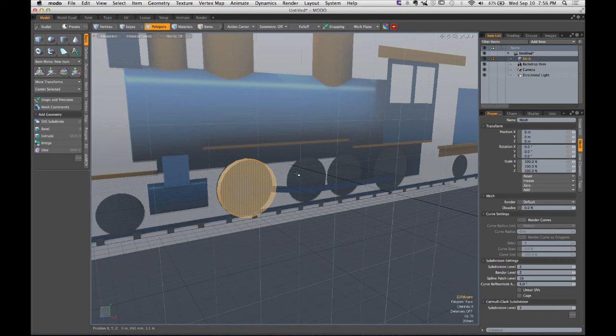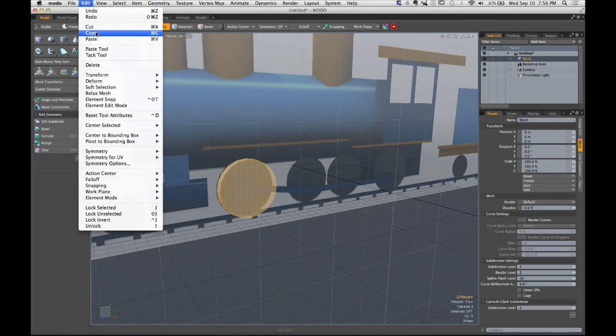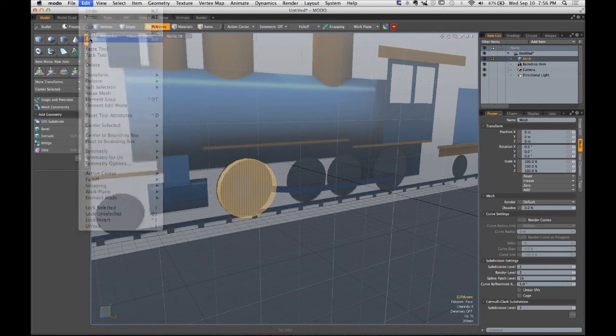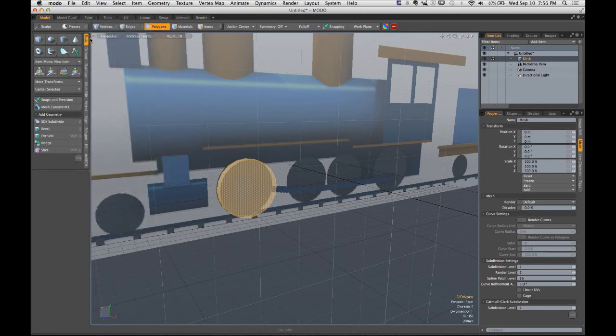With my shape selected, I can simply go to the top of the screen where it says Edit, choose Copy. Keyboard shortcut Command-C, just like on Microsoft Word. Now, I'm going to copy those polygons, and then almost immediately after I'm done, I'm going to go back and choose Edit, Paste. Now, it looks like nothing's happened, but what we've done is we've copied those polygons back into their current location. Before you click and deselect, fire off the Move tool. And move back your second duplicated shape. Now I have 2.